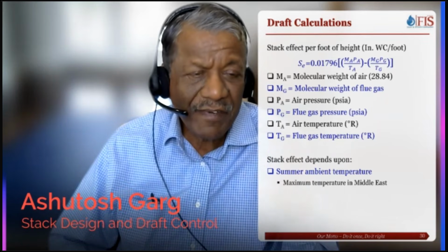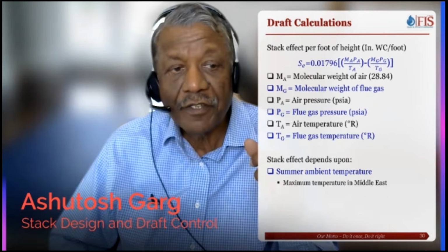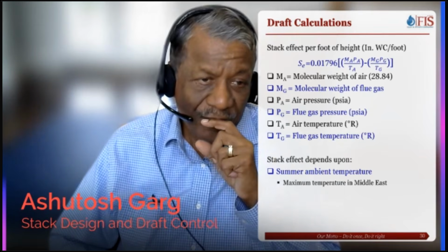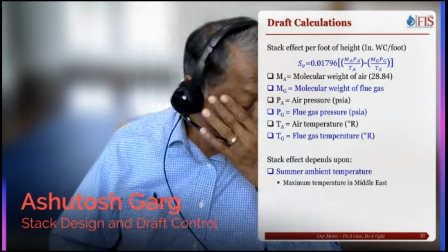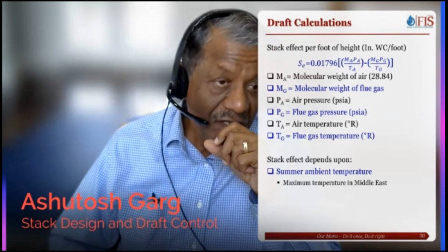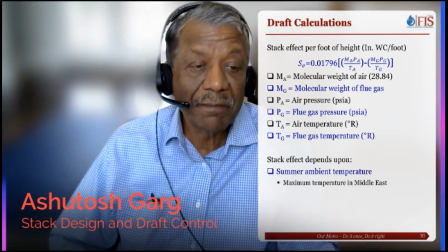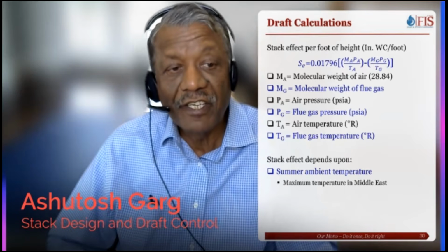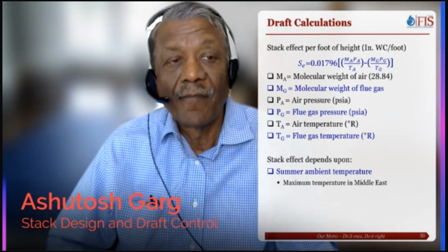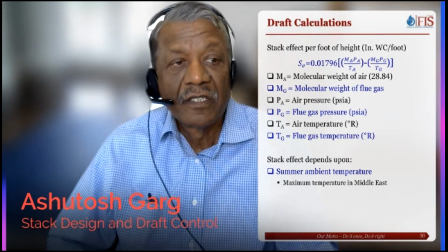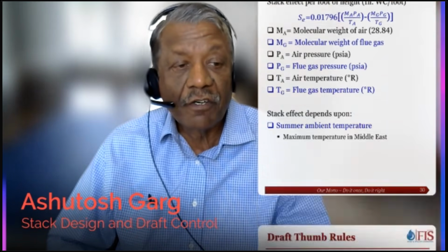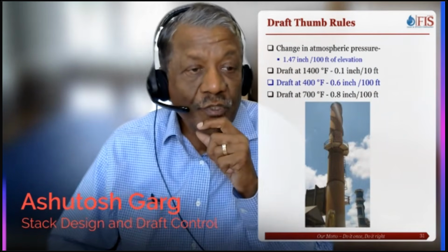So stack effect depends on the summer ambient temperature. And if you're doing a project in the Middle East, make sure you take the maximum temperature over there, which could be 120 degrees. Stack effect also depends on the altitude of the site.